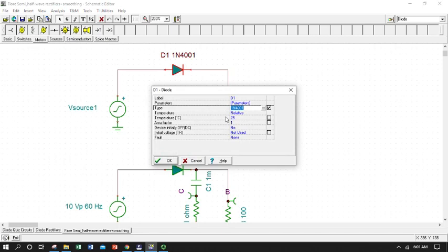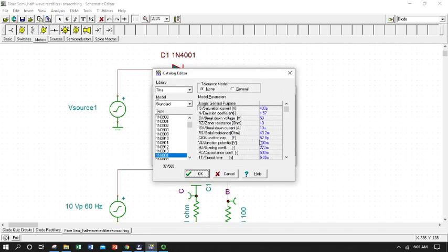The answer might be in the voltage specs. So I can go into my simulator and I can double click on my diode that I selected and go to the type, and there's 3 little dots that show that I can get more information. I click on that and I get a little mini spec sheet. So these are the actual performance parameters that the simulator is using to give me the behavior in my simulation. So it's really simulating a real diode.